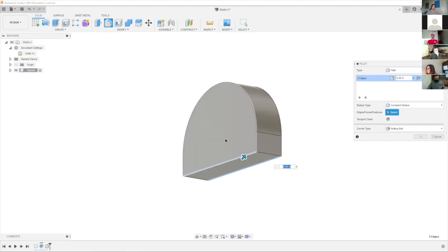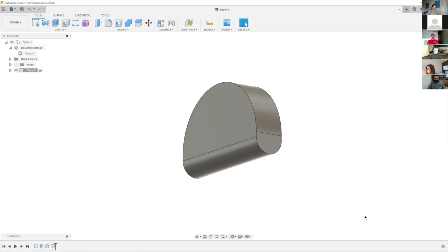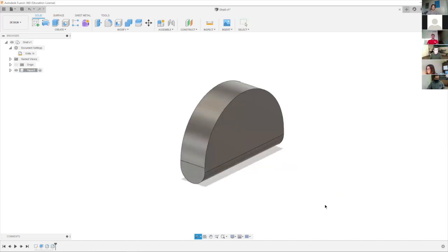And that'll allow you to view the other side of it and select that. And since we did 1.5 inches for the bottom, we can either drag, or we will type in 3/4 or 0.75 inches. And once again, we'll hit OK. So our taco is really beginning to take shape.